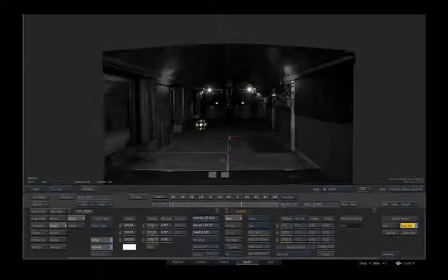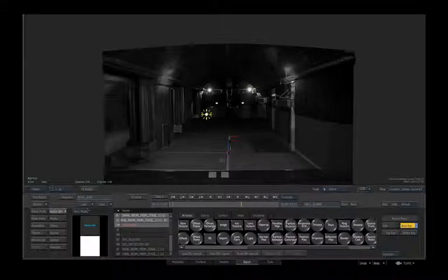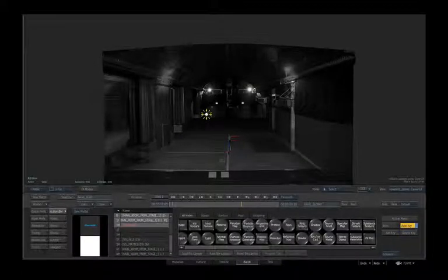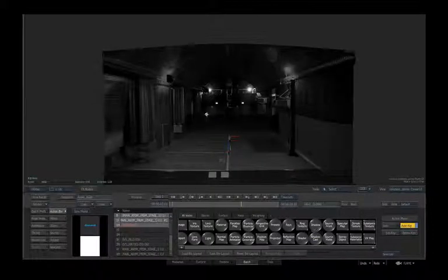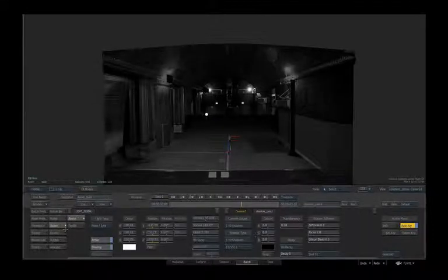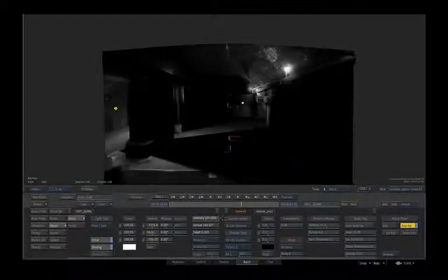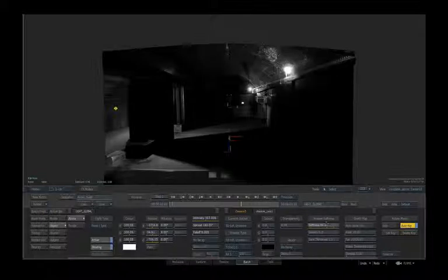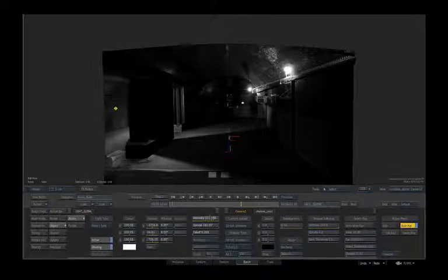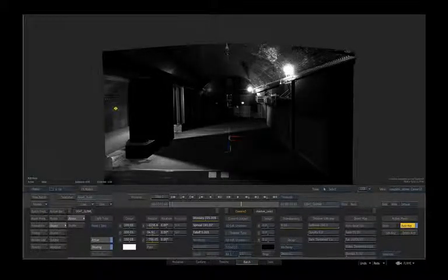One really cool thing to do would be to introduce a shadow caster on this light. So just with a little soft shadowing here, I'm going to set my light to sit over on the side, and you can get an idea as to how you might get some quite dramatic lighting effects going this way. Setting up some soft shadowing, or indeed if you wanted semi-shadow, you could do that too. Just a really neat way to relight your environment using the geometry.